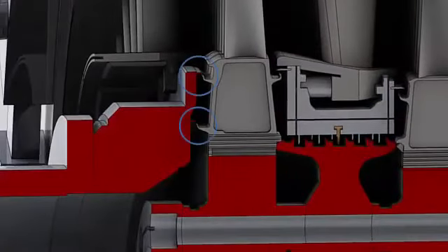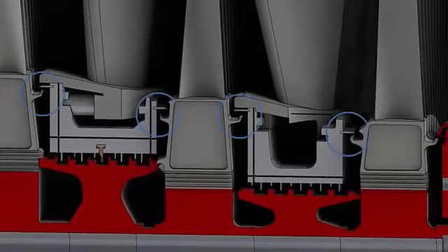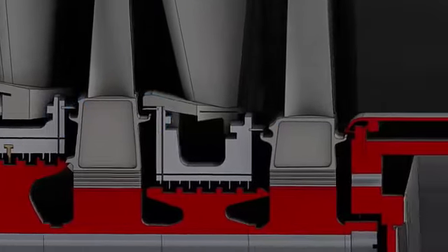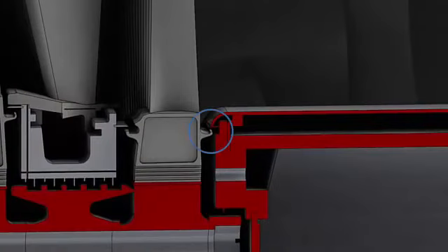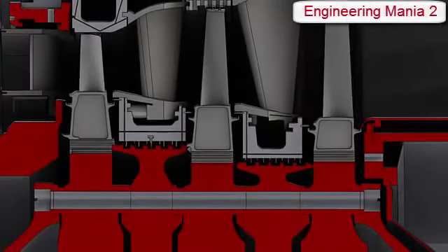Seals from the first stage nozzle support ring mate with sealing wings extending from the forward side of the first stage bucket shank. Also, seals from both sides of each diaphragm mate with sealing wings from both sides of each bucket. The seal from the exhaust frame mates with the sealing wing on the aft side of the third stage bucket shank. All these seals reduce leakage of the hot gases radially inward to rotor parts, improving turbine efficiency and